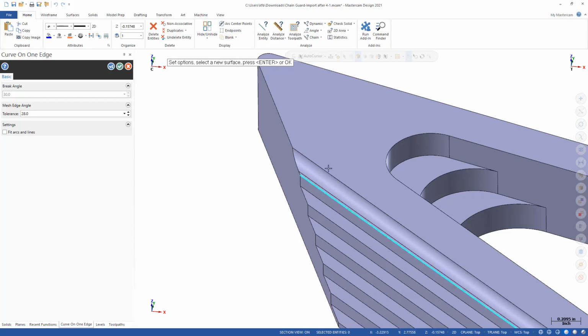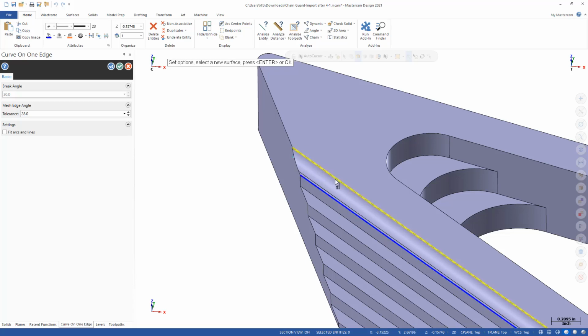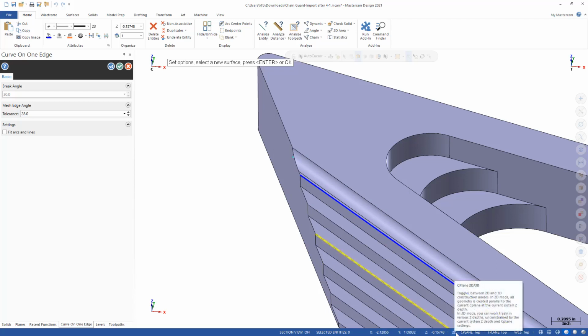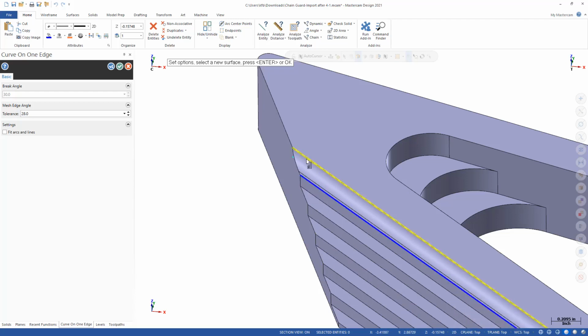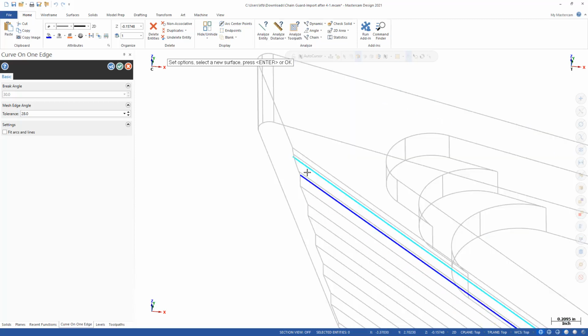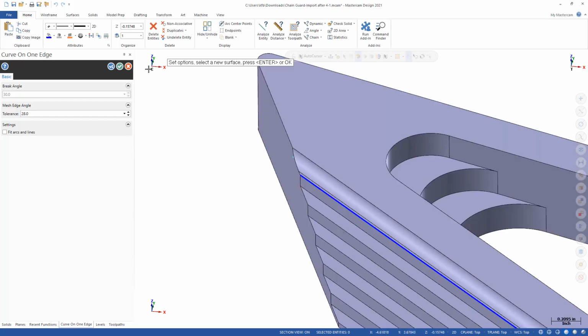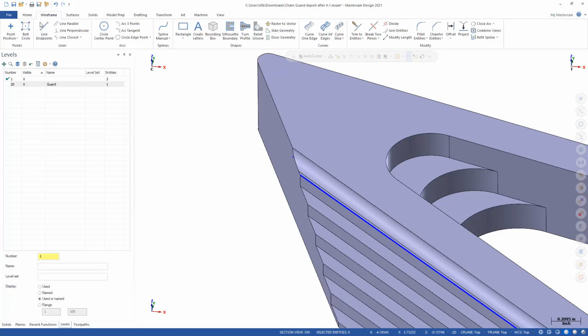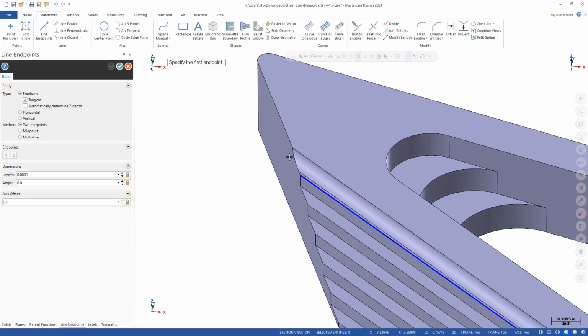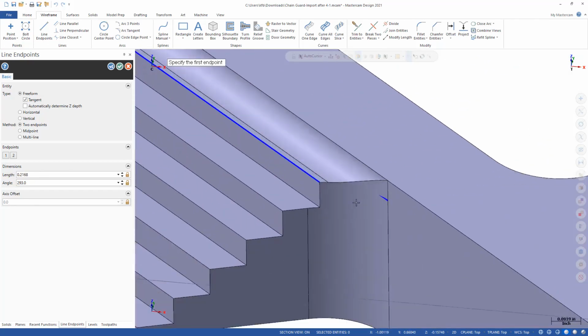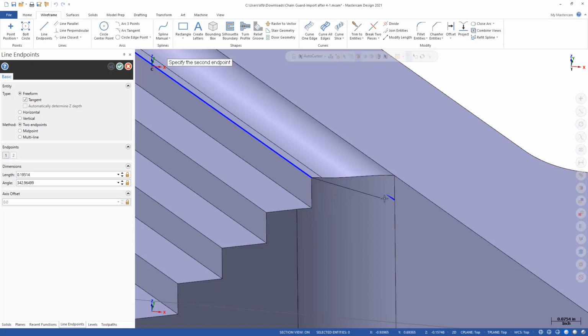I'm going to do the same thing up here. Now notice we don't see that edge, but it's actually hidden because we're in our 2D construction mode. So effectively this edge gets projected down. And if I quickly unshade my model, you'll see that the line is in fact there. So now I'm just going to use the regular line tool and select the two ends of these so they can be connected. Really, we're just creating a shape that can be used as a cut extrude.